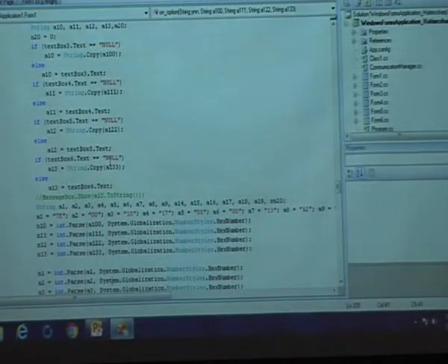In the beginning of the program execution, sir asked me about one frame to be sent to make the remote ZigBee on and off. The frame command consists of this particular value only. 7e is the starting delimiter, 0010 is the length of the bytes of this particular frame, 17 indicates making digitally on, that is the command that follows. So through the program you are ultimately creating a frame, and that frame is to be written to where? It is to be written to the serial port.